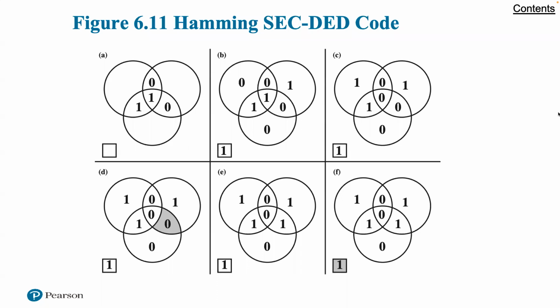Okay, I believe I just found an error on that chart, so I corrected it. So it's a SEC-DED code. Sorry for that, but I'm trying to make that change in real time here. Figure 6.11 illustrates how such a code works. Again, with a 4-bit data word, the sequence shows that if 2 errors occur, not 1 but 2, figure 6.11c, the check procedure goes astray and worsens the problem by creating a 3rd error, E.